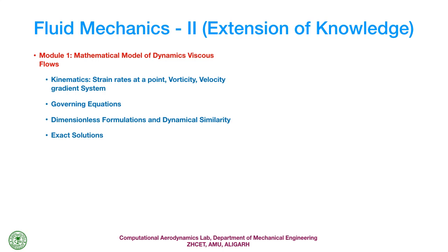That is, it is only valid for inviscid flows. So that is why the Bernoulli equation cannot be applied to viscous flows. Now we will add to this knowledge, and we will show you how the viscous forces should be modeled, and we will come out with a complete equation which is going to model any incompressible fluid flow problem.